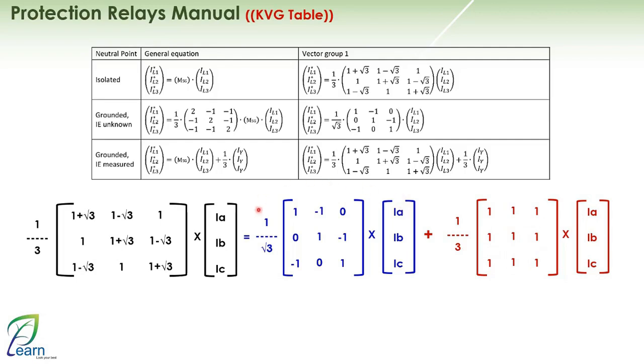It's as if you've combined your regular currents with the regular compensation matrix plus the neutral current, which is added each time. So if I go back here, it means that if the current has been read, and we will see this when we apply it to the current that has been read from the CT installed on, in this case, how will the relay handle it?